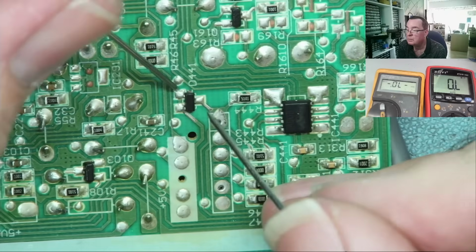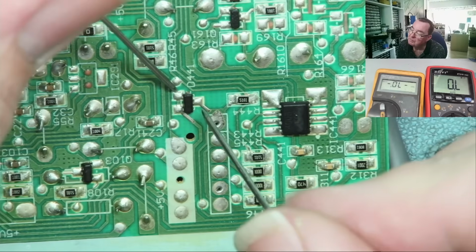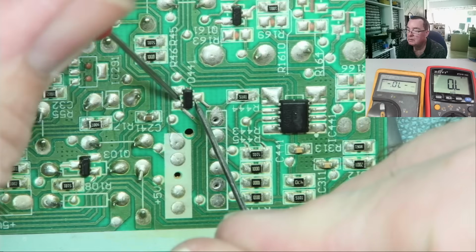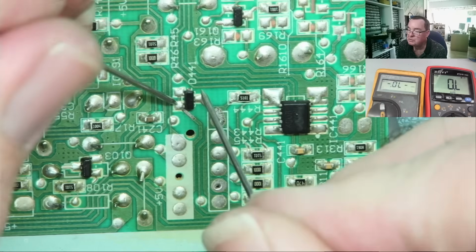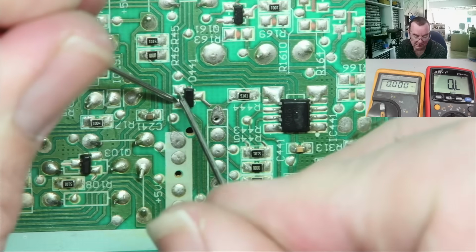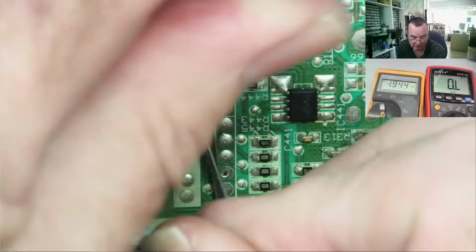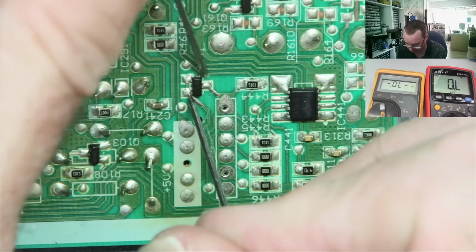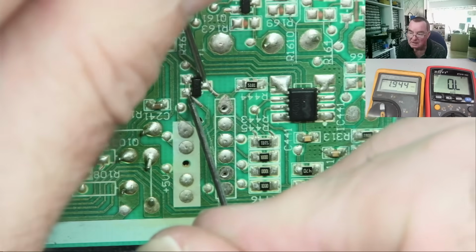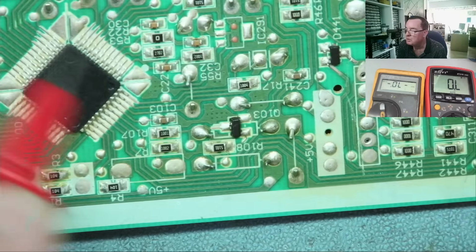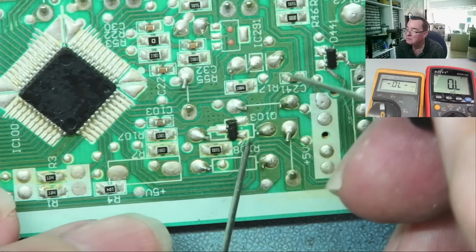This one, what we got? Diode by the looks of it. So diode, and these two are connected together anyway. Now you could connect the other way to make it read kind of like open or higher, but I mean, if you read a diode across it, it ain't short and it ain't open. Yeah, so it's probably not worth measuring the other ones.